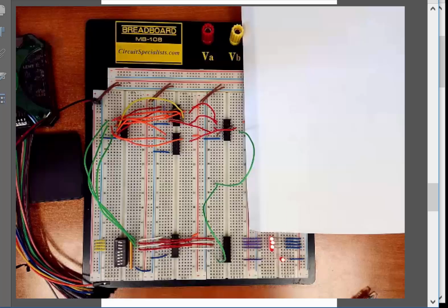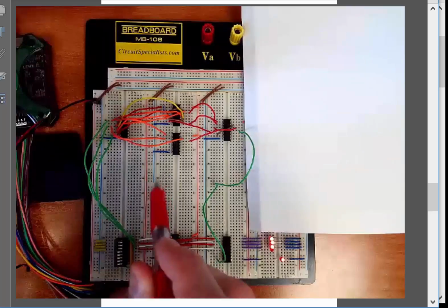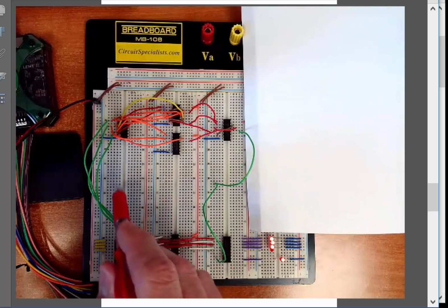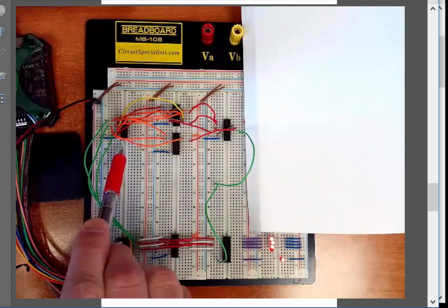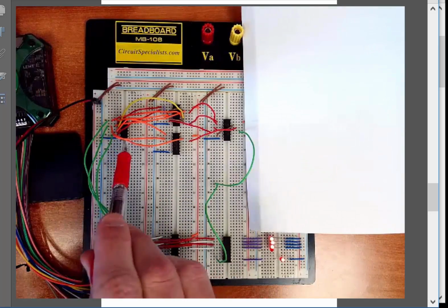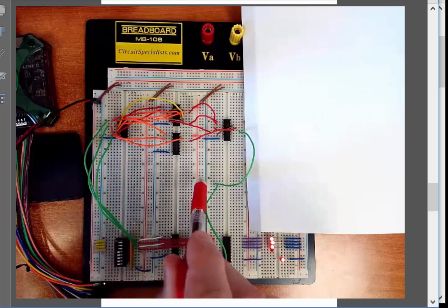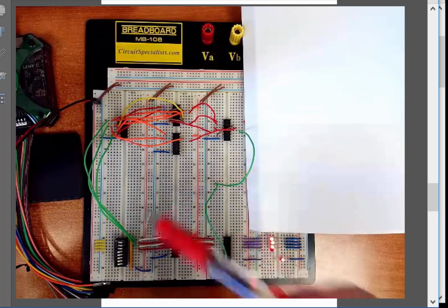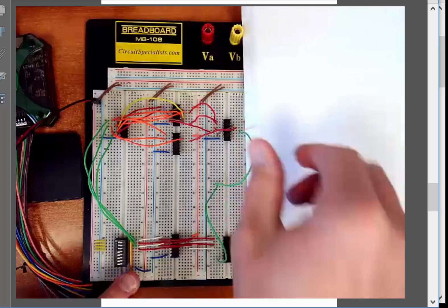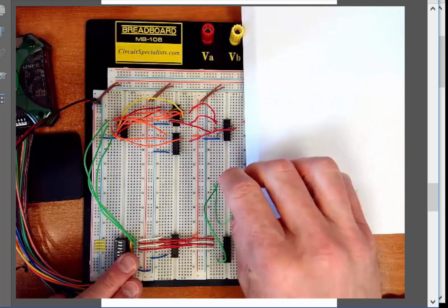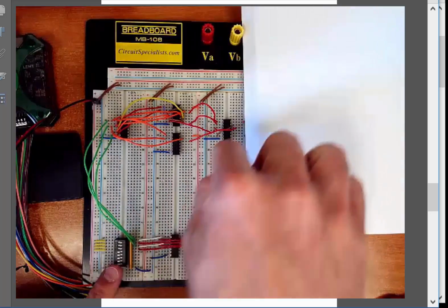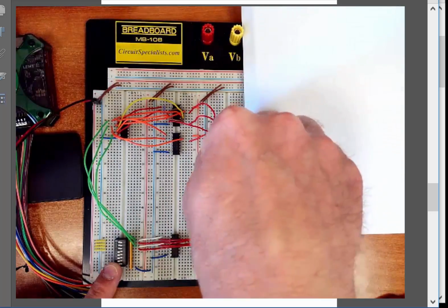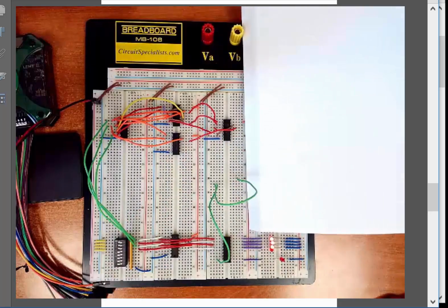Deliverable number 5 is that you are going to come back to your breadboard and build that circuit. When you do it, leave space on your breadboard to build the circuit right here. You can leave your inverter right here and reuse it, or you can move it down if you want. You'll have space right here to build your product of sums. This will be your output, and you're going to test that circuit. It should be identical to the sum of products functional behavior. It's just done in a different form. Take a short video of that, and that's deliverable number 5.